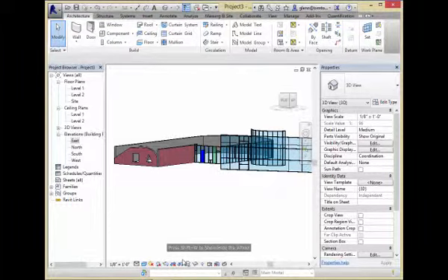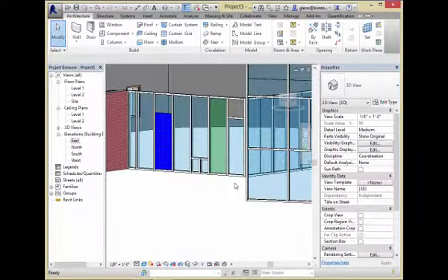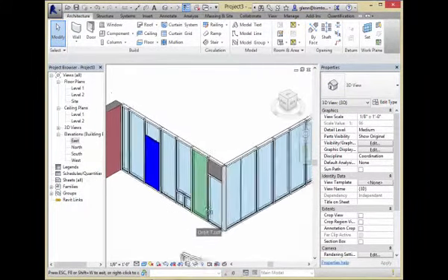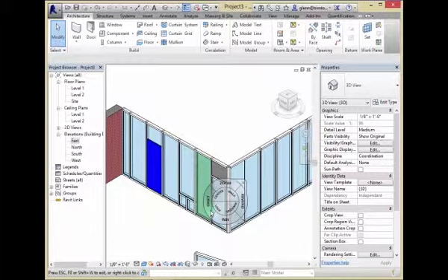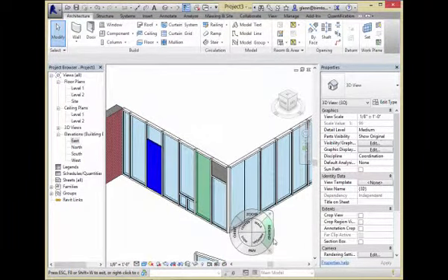Again, the last thing we'll show you before we break is based on a question we had at the first session this morning. Someone came up with a brilliant question. Hey, this is okay, but if I have a couple of different panel types, is there a way to really quickly copy that over to other panels? Otherwise we'll have to go in and choose them and change the type, choose them and change the type, choose them and change the type. And there is. There's actually a tool which is all about that.